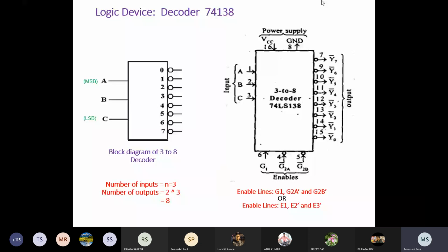You may ask why more than one enable line is required. It is very useful if the number of address lines of your memory is less than the number of address lines of your processor. When you design the circuit with the help of this type of device, you will understand why you need more than one enable line. I hope you understand this part. This is what you have studied in your digital electronics class, which I have explained here.